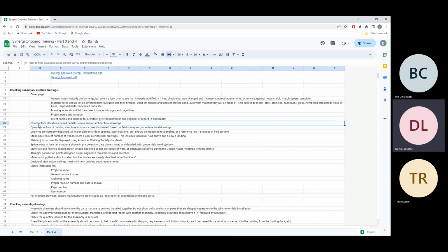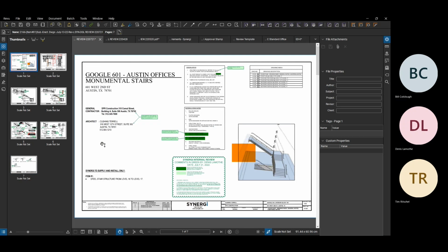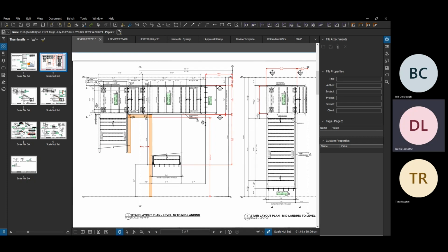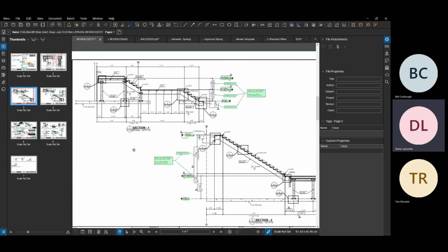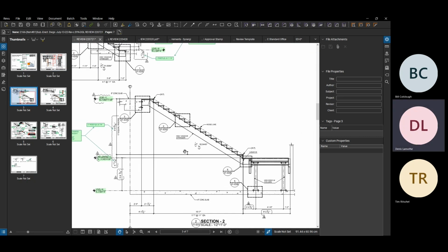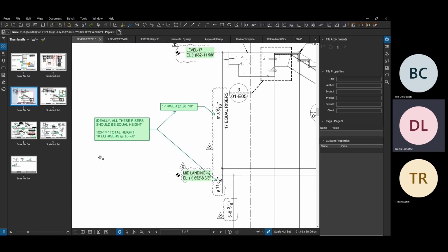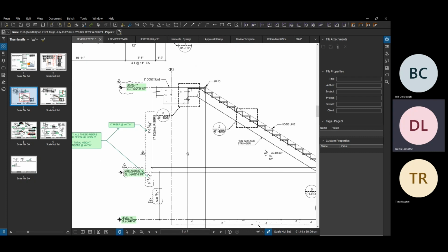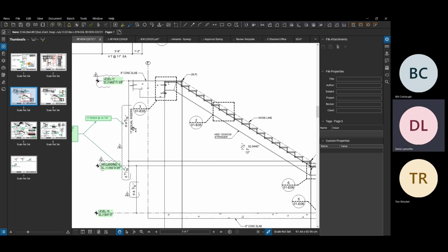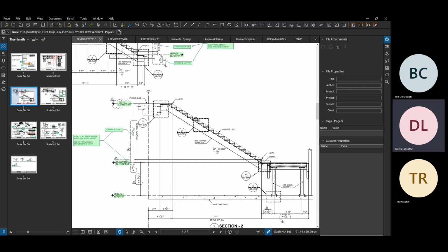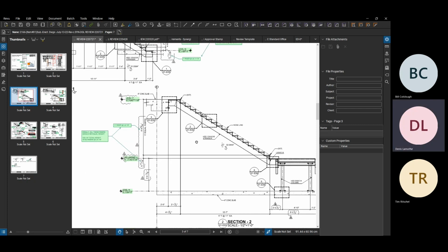And then for the rest of the drawings, loosely speaking, we're checking everything. The big things to check are the grid lines, the stair on plan, and the floor-to-floor finishes in elevations, that they match either the architectural set, or if there have been some changes on the field dimensioning part, especially more relevant with the floor-to-floor, that those changes have been incorporated. In addition to checking dimensions, we're going to make sure that risers and treads are all equally divided on a flight of stairs. So that's important as well.